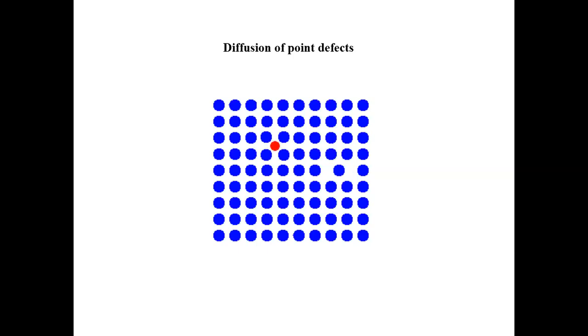And we're going to talk about each type of diffusion in detail. We're going to talk about interstitial diffusion, vacancy diffusion, and even self-diffusion. Okay, now what is self-diffusion? If you look at this, there's a particle that can move into the vacancy site. That is called self-diffusion.